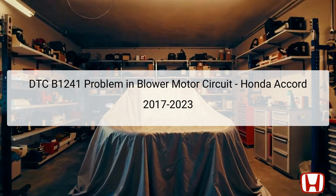The Diagnostic Trouble Code, DTC B1241, also indicated by the error code 59, signifies a malfunction in the blower motor circuit of the Honda Accord, produced between 2017 and 2023. This issue can affect the proper functioning of the vehicle's climate control system, specifically in terms of air distribution within the cabin. The blower motor is a crucial component located within the dashboard area of the vehicle, typically near the HVAC, heating, ventilation, and air conditioning assembly.